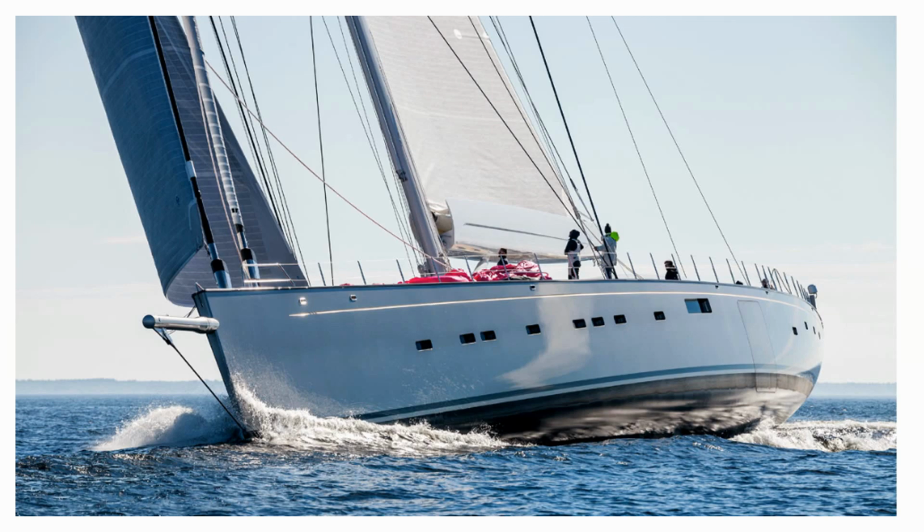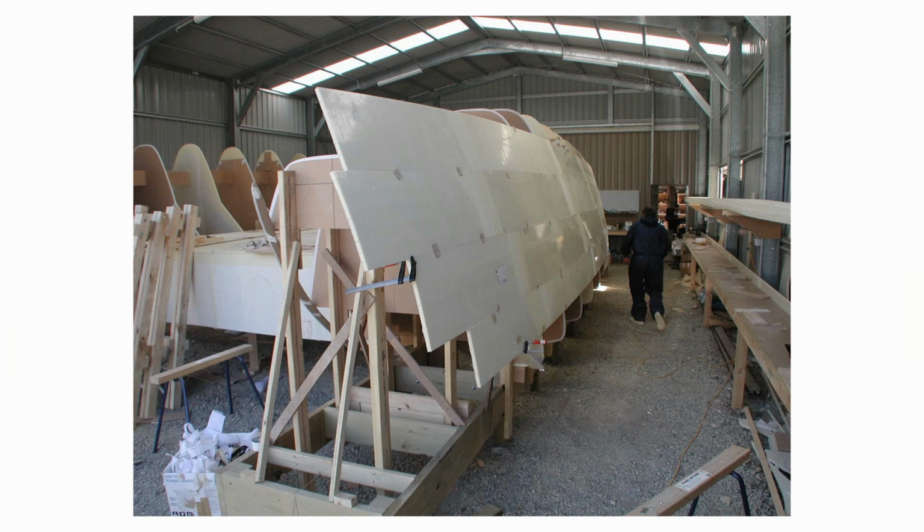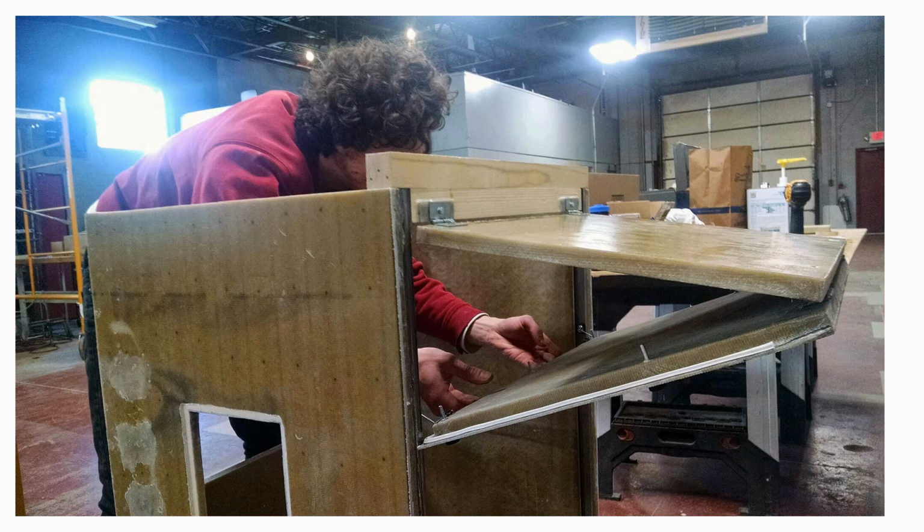So how do you build a flood-proof building? We started off, we said, well, how about a boat? Boats are flood-proof, right? And they're made of something called structural insulated panels. You have two skins of, in this case, fiberglass, and you have foam on the inside. Now, for boats, the foam is for buoyancy, but it also resists heat flow. So we thought, oh man, we're geniuses. Let's just make a boat as a house. And we went far down this route.